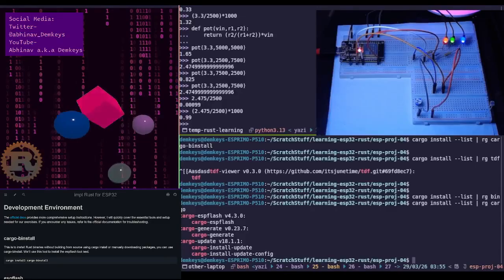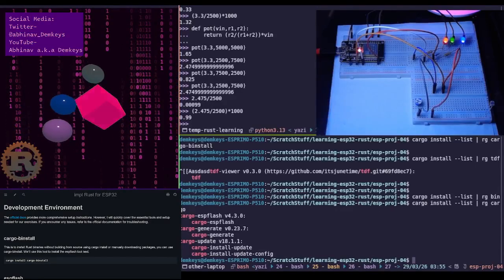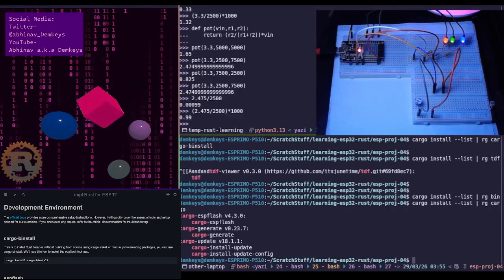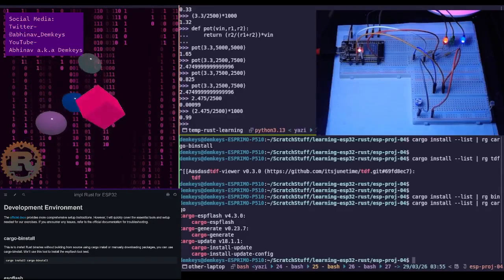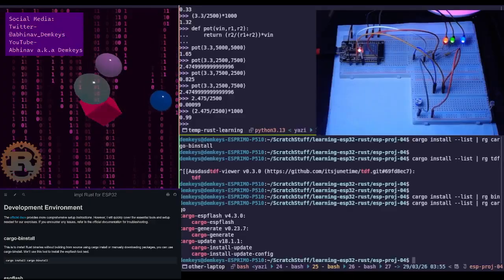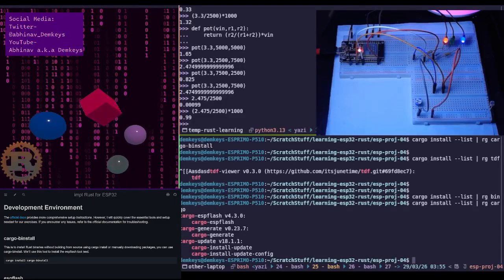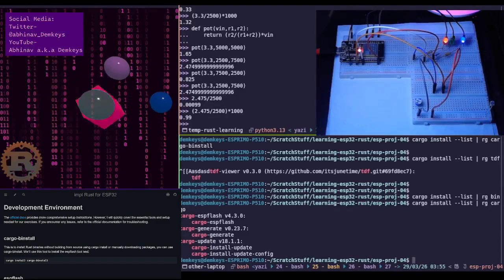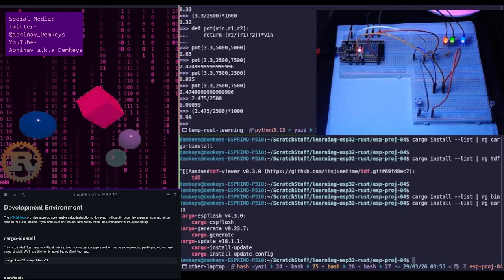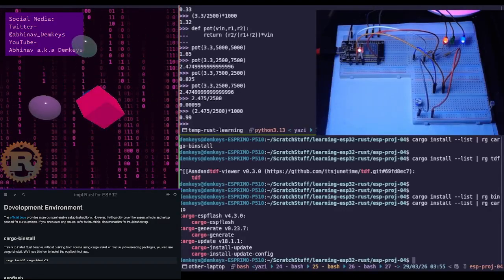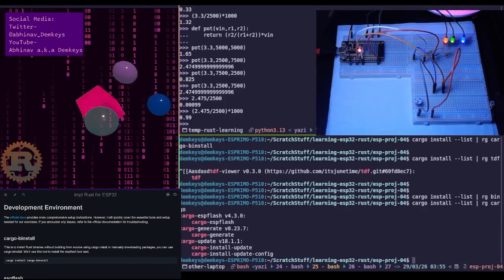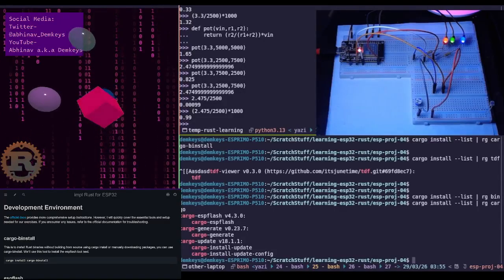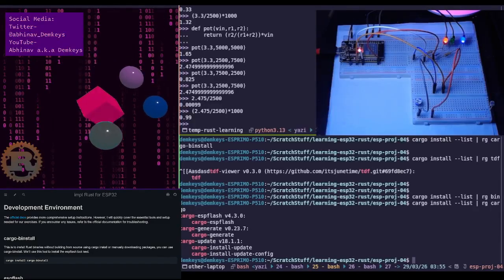And then now you have this back EMF thing, which also comes up when you are learning about DC motors. Because when you are setting up a DC motor circuit, assuming you're not using a driver module, a lot of times they'll mention something called a flyback diode, and that is apparently supposed to help protect against this back EMF thing, so you don't send a massive current slash voltage back.